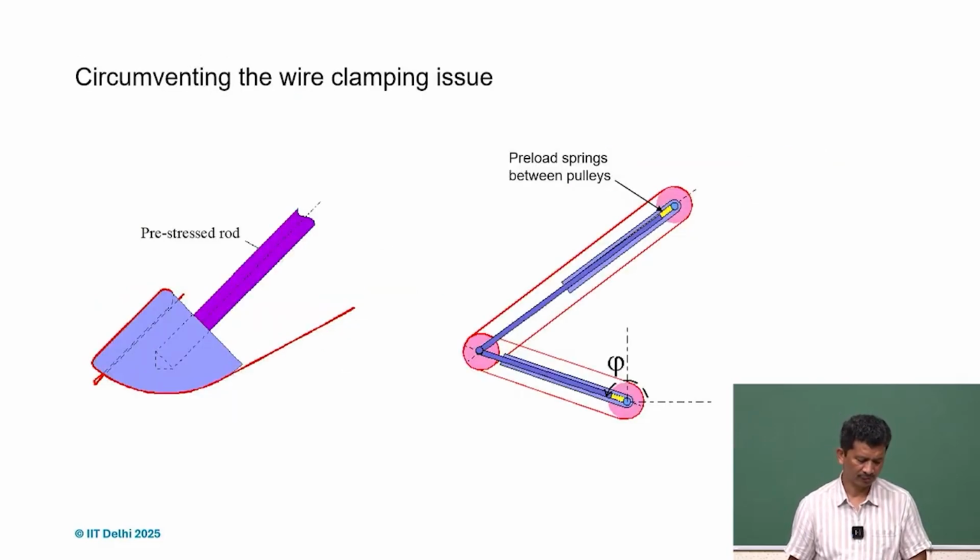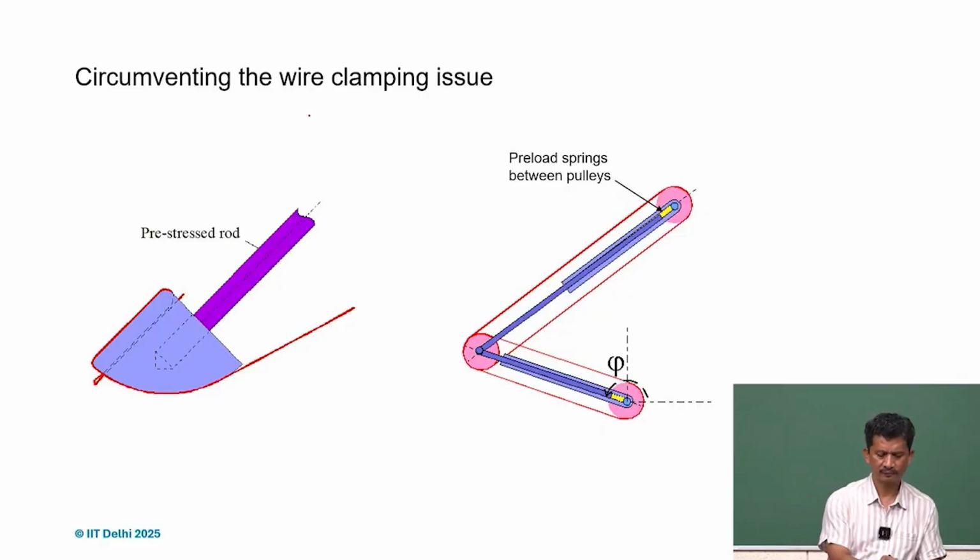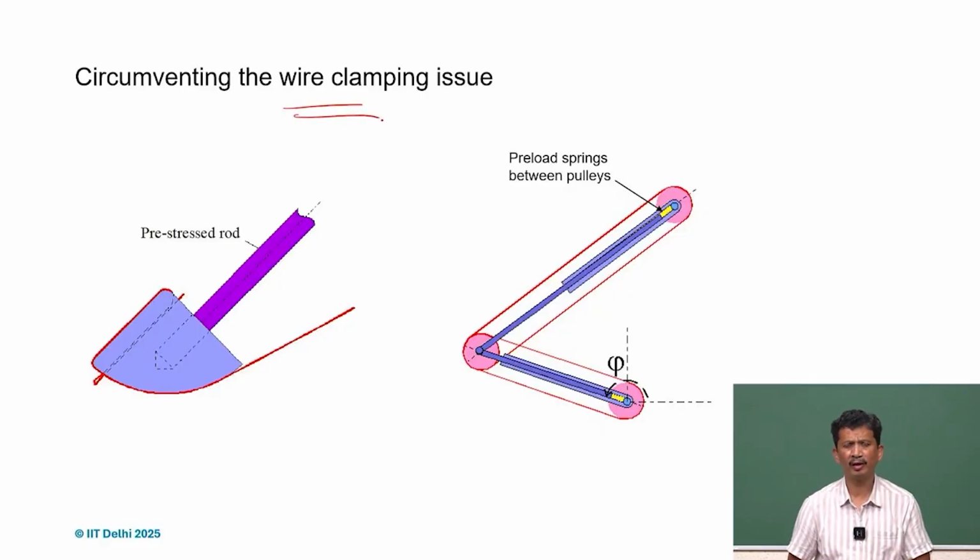So what we also realize is that a simple flexible wire can also provide us the required constraint in one direction. So if it's in tension, and if we can ensure that the loading in the wire is always in tension, it can also give us a very good constraint device or constraint mechanism or compliant mechanism, what we can say.